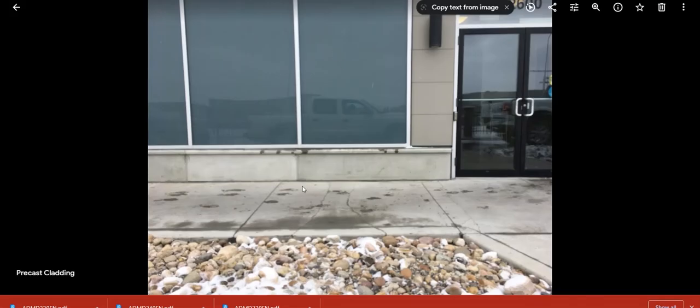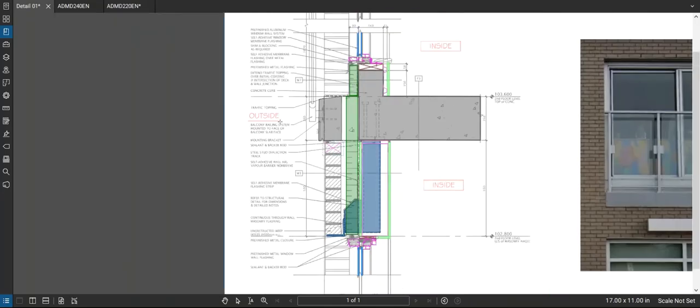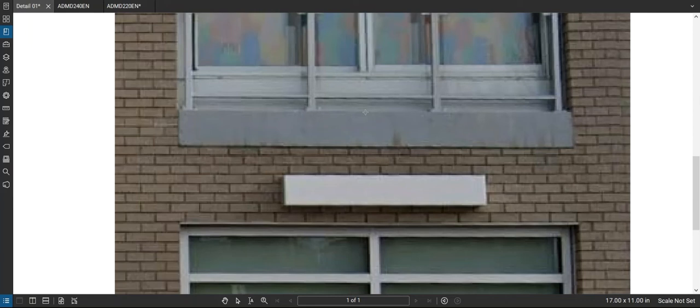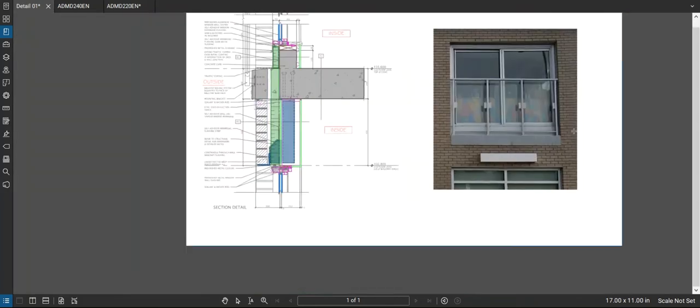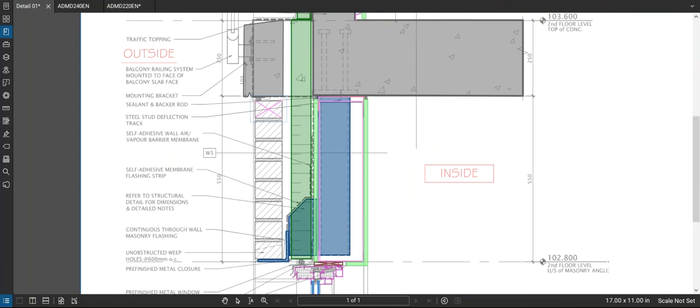And the reason I'm suggesting that is because the precast concrete element, if we look at the picture we're dealing with, it would just be one element, probably. It wouldn't even have a joint in it, so it's kind of difficult to get some vent holes at the top. So you'd be putting the vent holes in the brick, top brick in this case.